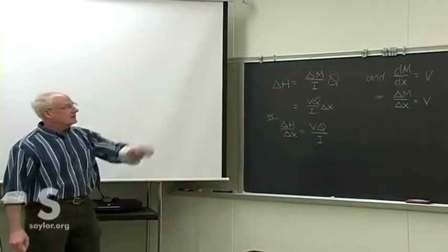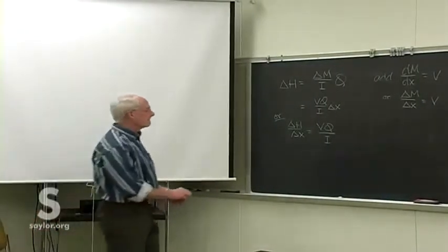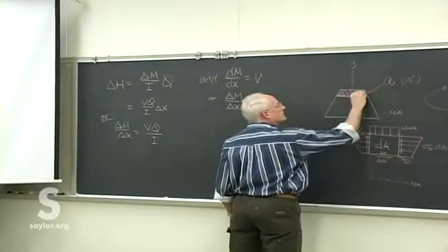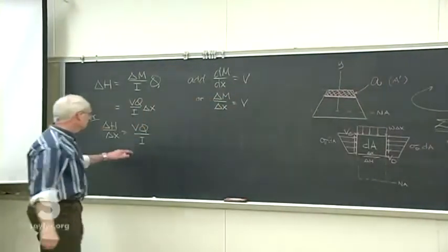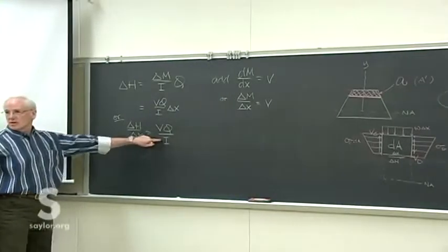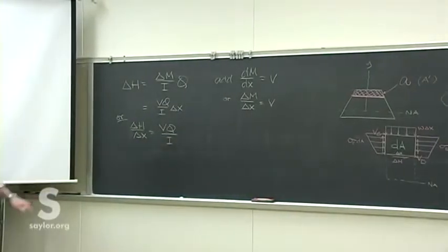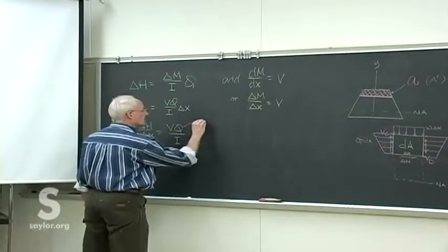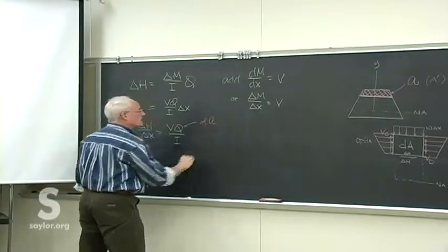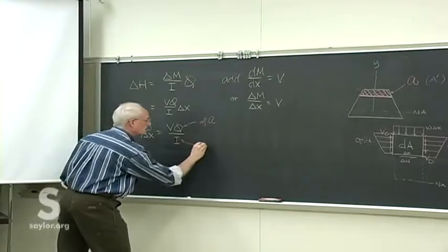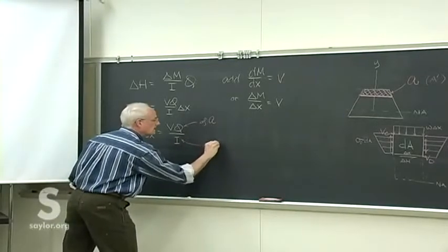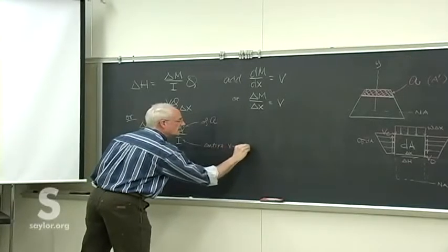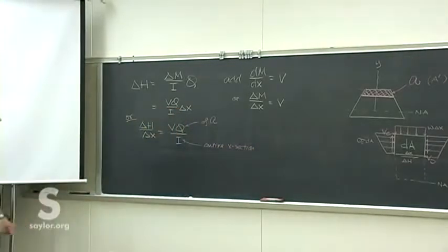Q, remember, is the first moment of area of the section above our plane of interest. And then I is the moment of inertia of the entire cross-sectional area, the entire face. That's as tricky as anything for this, those two pieces.